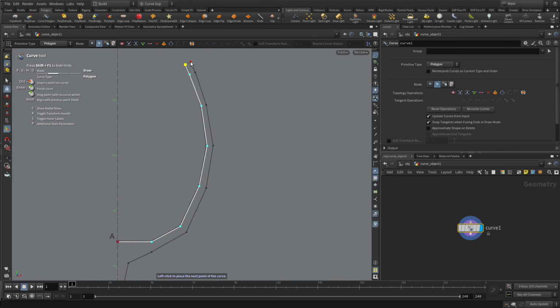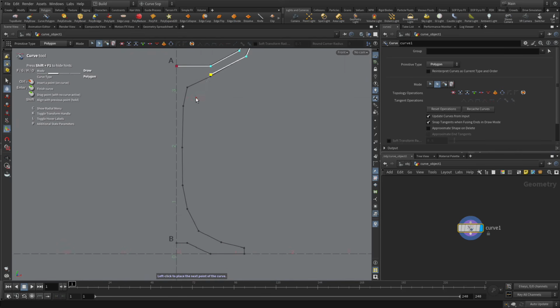We're just going to go around and we're going to click around to use the dots on here as a guide and get the wineglass that we're looking for. And at any point you can press the space bar and move and continue working. As we go along, we click here, and we want these last four points to again use the grid snapping. So we press and hold the X key, and now we've got that again. So press and hold, and then enter.